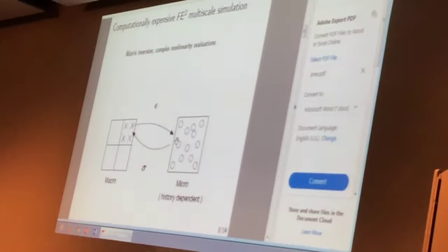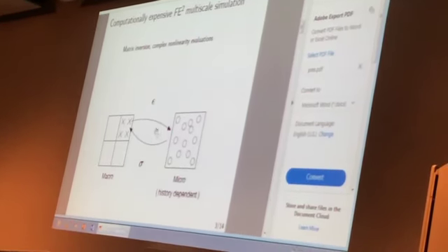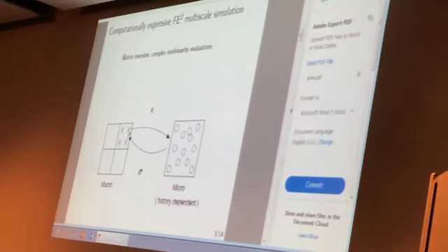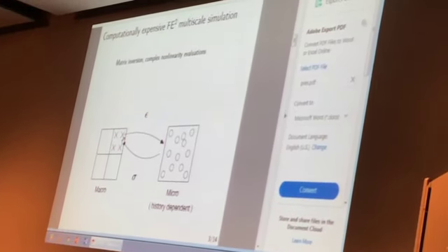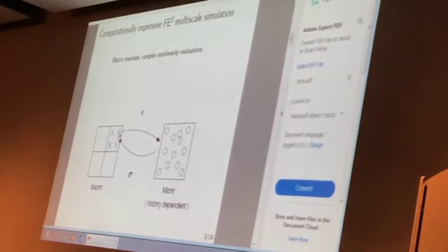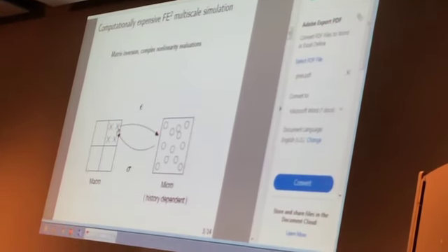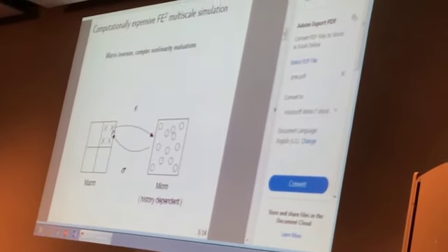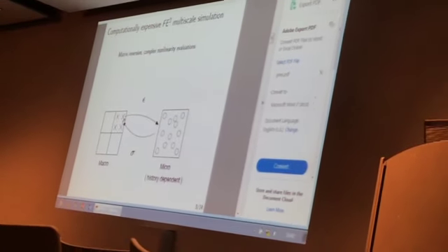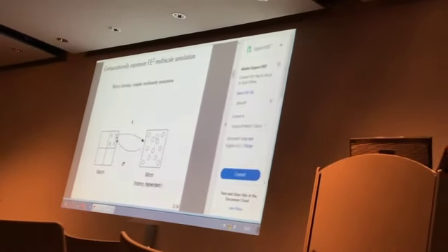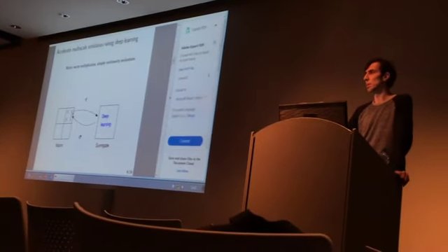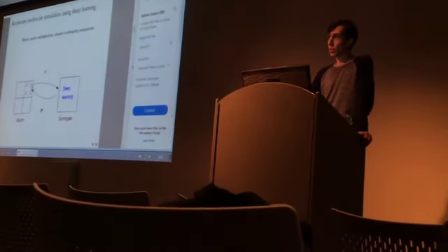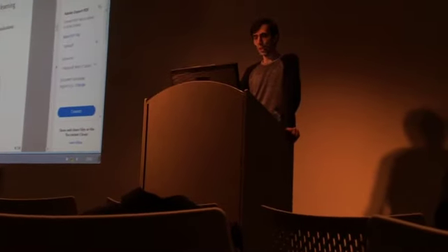The reason is that at each integration point in the macro model, we are solving a finite element simulation. And a finite element simulation has matrix inversion and complex nonlinearities to evaluate, for instance, plasticity. We can accelerate this process by replacing the micro model with a surrogate, a deep learning surrogate.